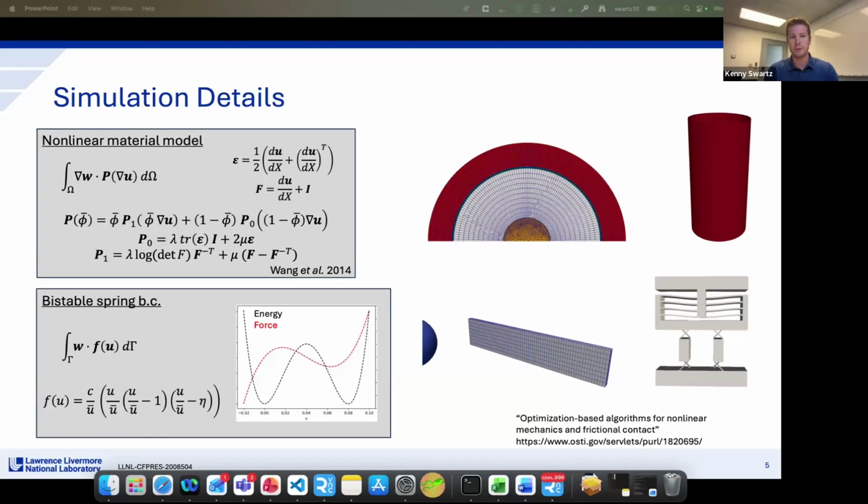But as we know, when we bring in a nonlinear material model such as Neo-Hookean, the void elements can create quite a headache, and we get a lot of numerical problems when they start tangling. And so I am employing here a technique that I found in the literature. The basic idea is that you use a linear material model for your void elements, but you use your nonlinear Neo-Hookean material in the solid elements, and you have this way of interpolating between the two, where specifically you weight the displacement gradient by your density field.